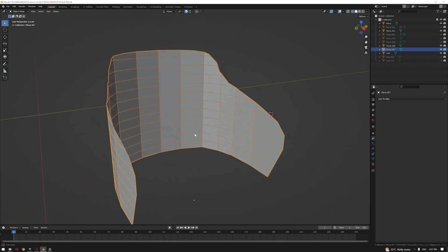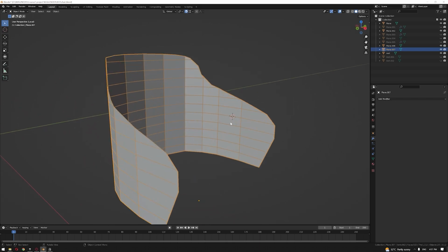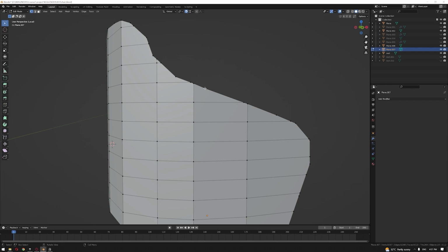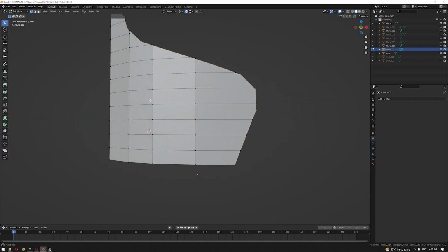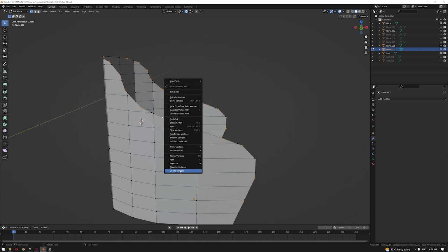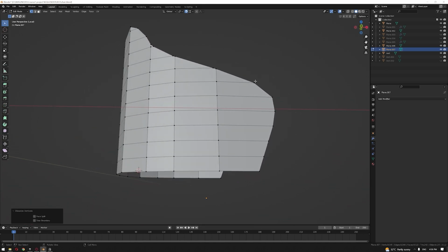Now we have the basic shape of the chair based on the base of that chair and the side projected shape. The first thing we're going to need to do is remove all the unconnected vertices. We can do that by selecting one of the vertices, select similar, and the amount of connected edges. It will select all the similar edges, just remove the bottom part which represents the basic shape of the chair. Right click and dissolve. Now we can also connect these vertices by selecting these two, for example, press J,